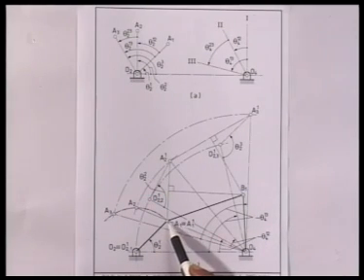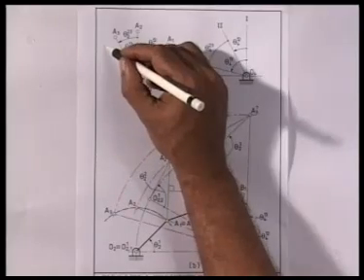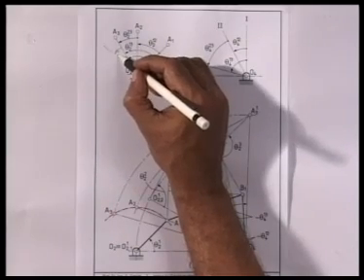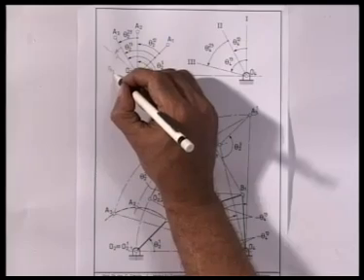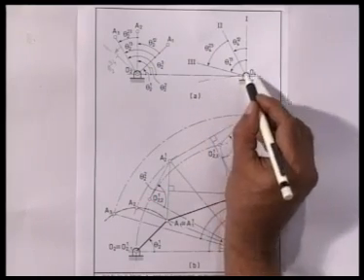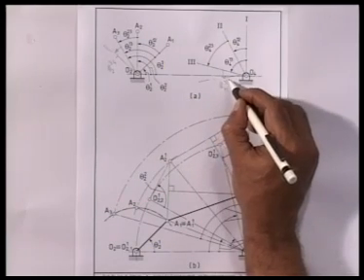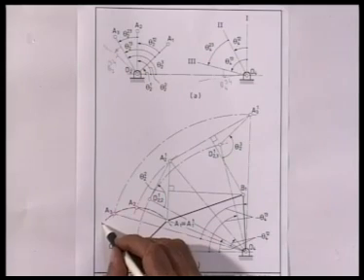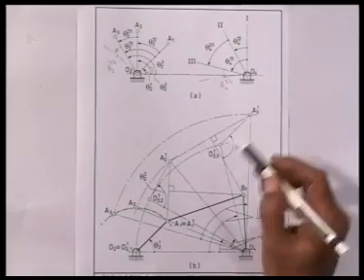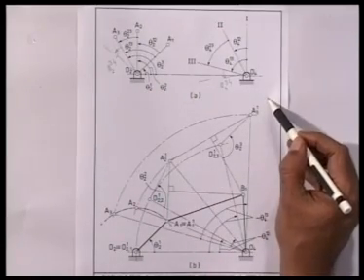So with such an arbitrary choice of A1, if I had one more pair of coordinated movements, say theta 2 3 4, and the corresponding movement here is say theta 4 3 4, then I could have located A4 on this circle, but the inverted position of A4 will be a fourth point A4 1, and there is no guarantee that these four inverted positions of A, namely A1 1, A2 1, A3 1 and A4 1 will lie on a circle.